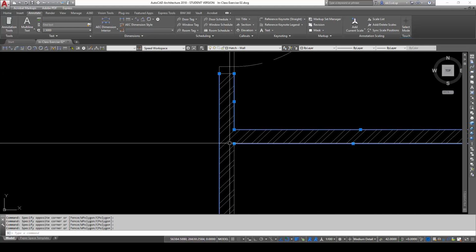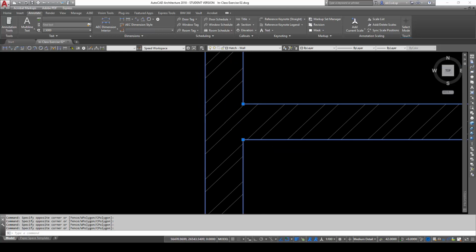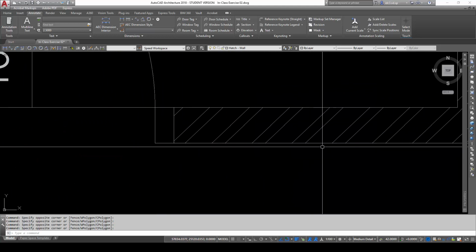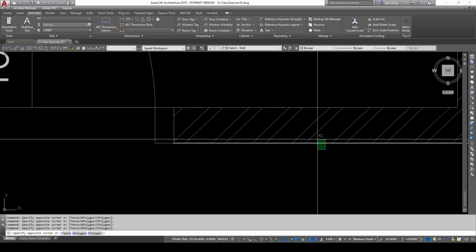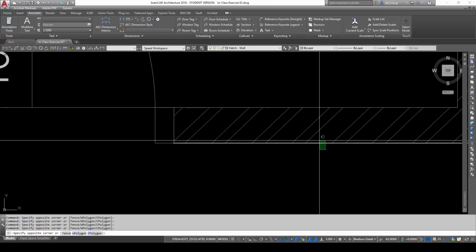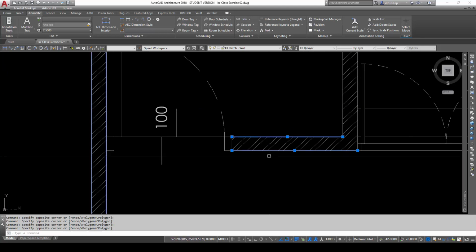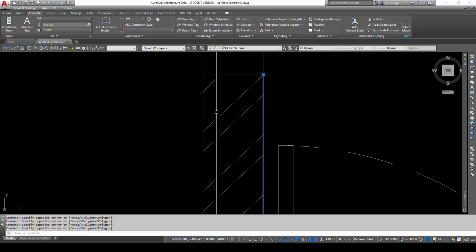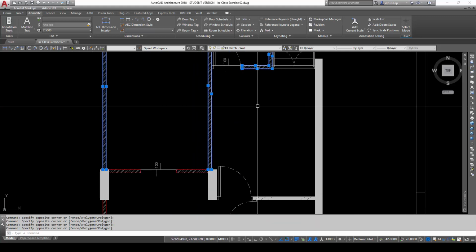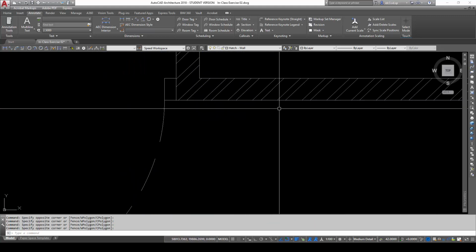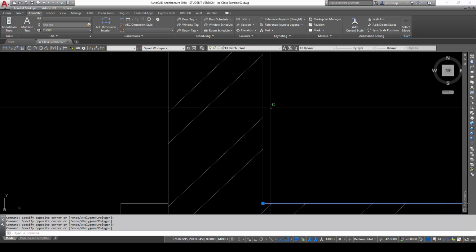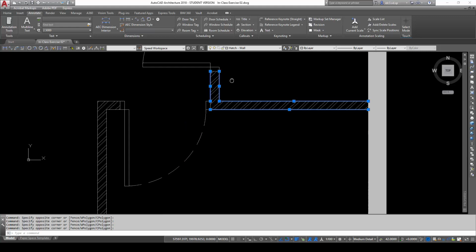You find that when you are using a lot of crossing selections, crossing selections are when you use the lower right hand, the green, notice here there is a green colored window. When you use crossing selections more, it tends to make our selection a whole lot easier because we do not need to select everything all at once here. Many a times in AutoCAD, I prefer to just use the crossing selection more than the window selection.